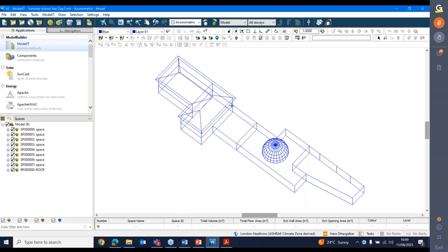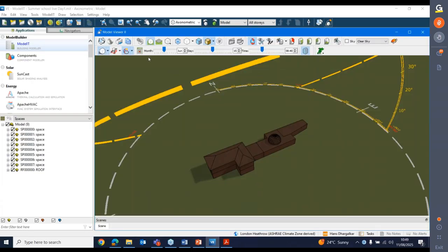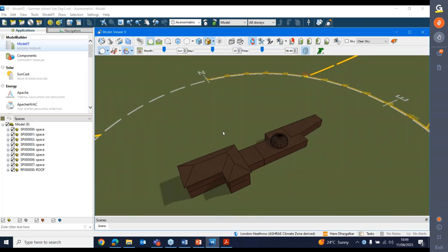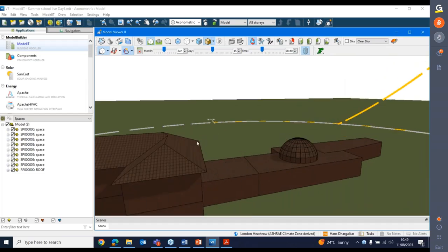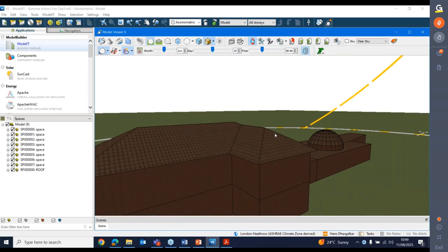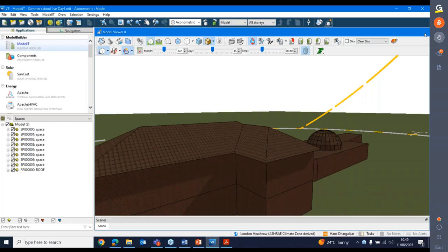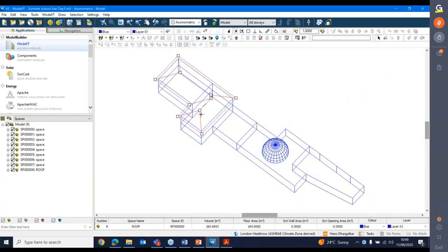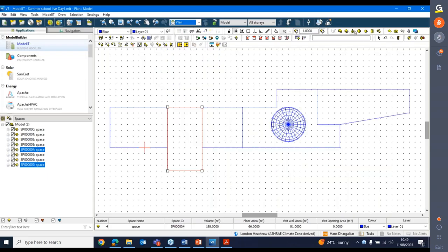Okay, so if I just go back to that viewer, and we zoom in here to that automatic roof generated, there you can see those ridges here and here at different heights, because you've asked for a fixed angle. So if you want to have a constant angle, you have to draw the roofs manually. Okay, so I'm going to draw a roof space manually over this space. So as I said earlier, I can't use any of these tools to do it in a plan view.